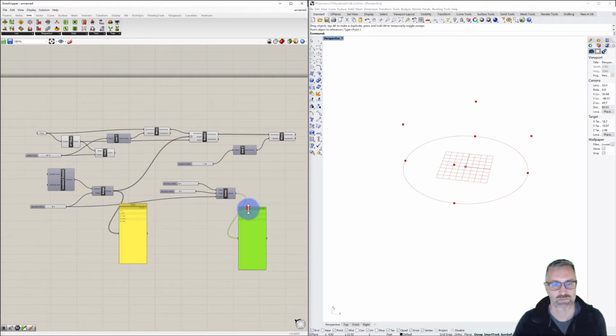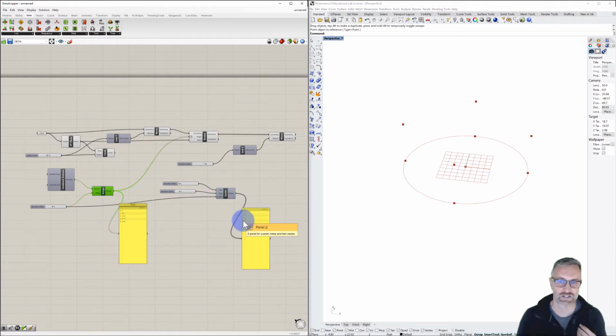And so we have a little bit of a problem, not a big problem, but I think it can be confusing when Rhino sometimes counts 0, sometimes doesn't count 0. So in the case of the range, when we plug in 4 to the number of steps, it's 4 steps in addition to 0. In series, when we plug in 4, it's 4 total. And so these two are off by a little bit. We can easily fix that.